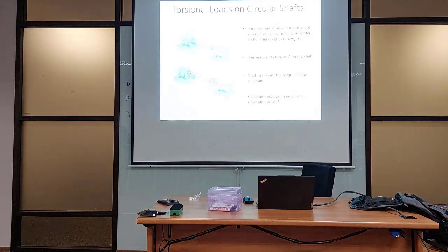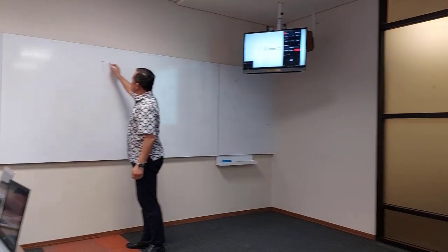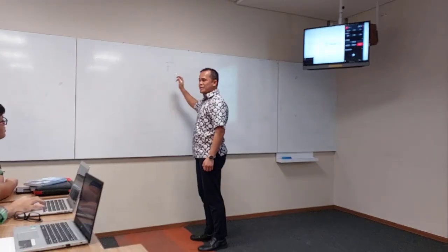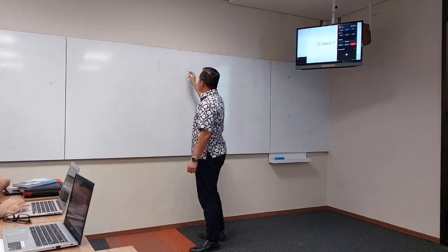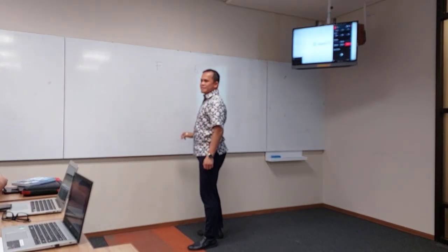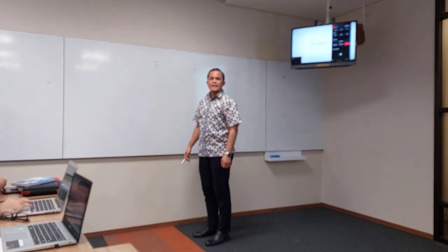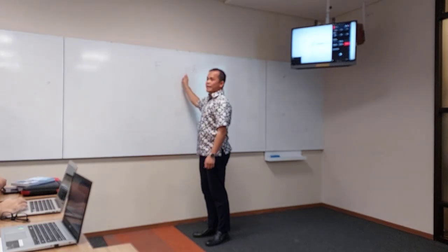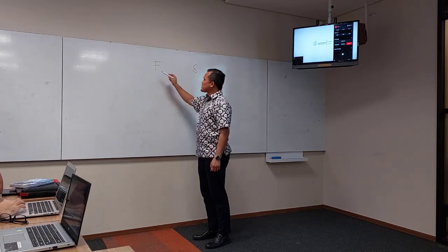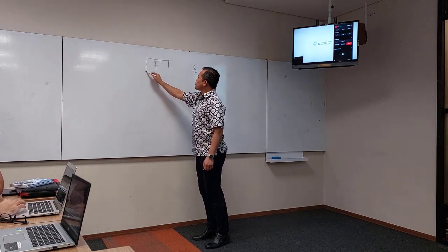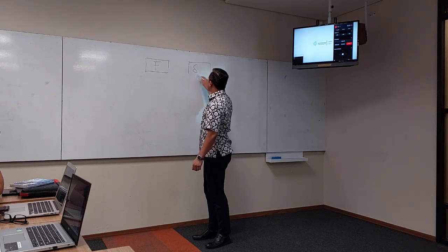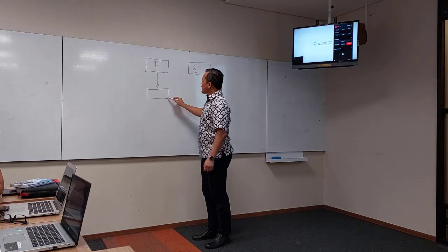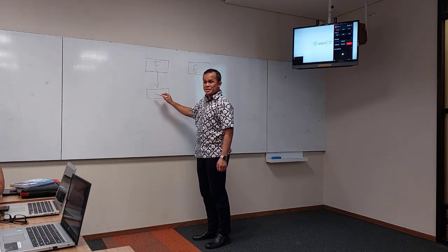Remember when we talked about F, this is F related to uniaxial load. This generates delta. Delta is displacement. You want to correlate these, but you cannot directly. What you do is you first convert force into stress.